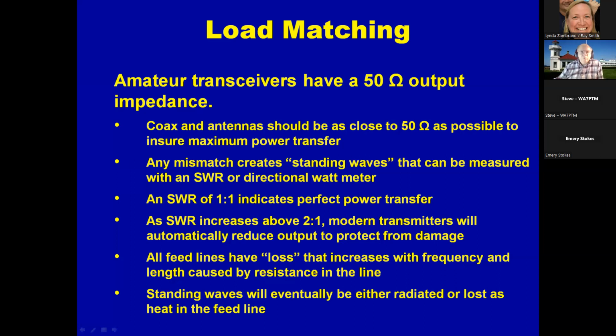We use a ratio to talk about the power out versus the reflected power, the forward power versus the reflected power. And we look at that ratio. 1-to-1 would indicate a perfect match. It's absolutely perfect. The higher the first number is, the less perfect it is.